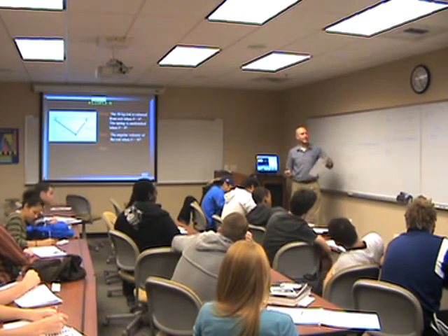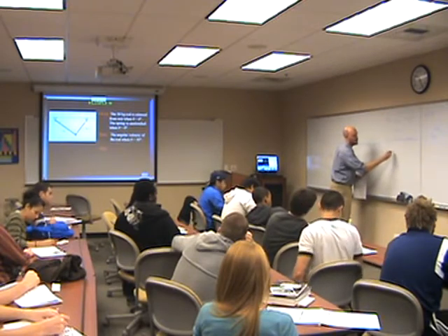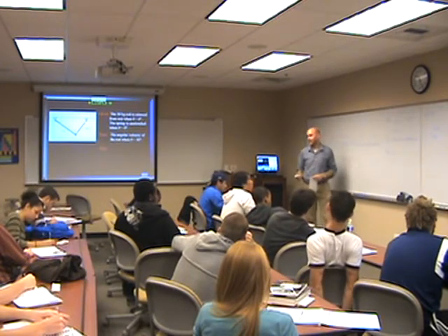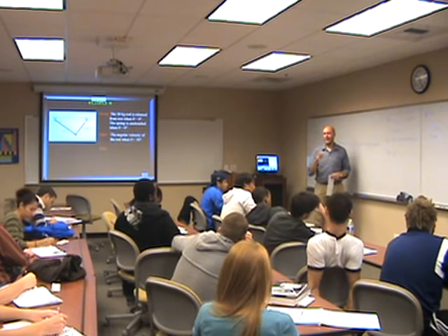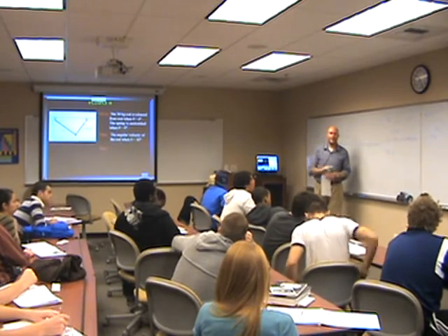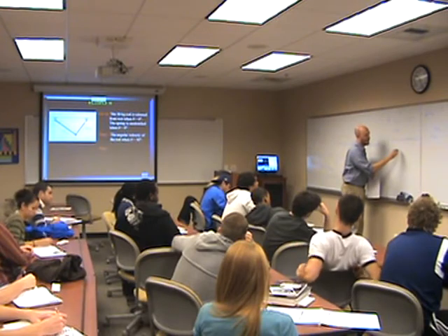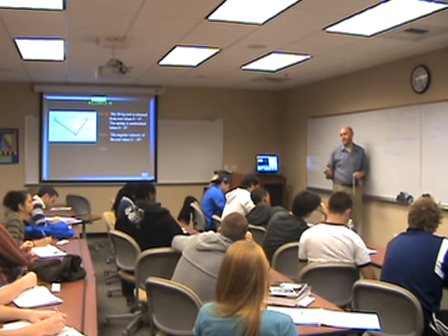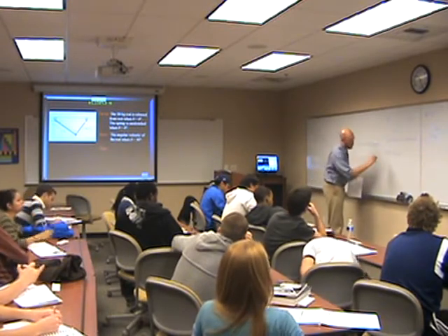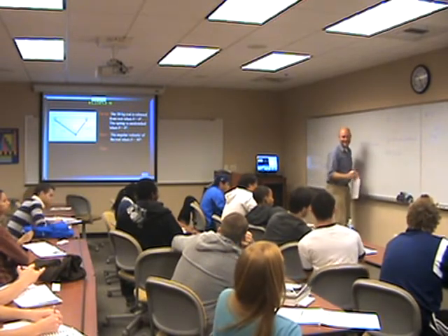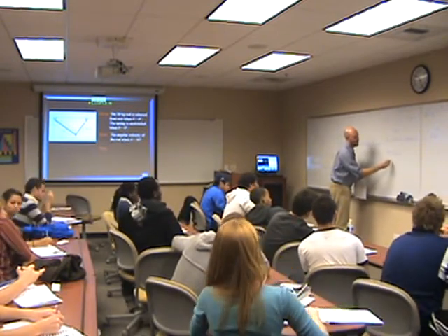It's equal to what? Well, initially it's 0 because we're at rest. So our final kinetic energy is 1/2 times what? Mass... well, I_G. It's 1/2 I_G, or we are rotating now about a fixed point, so we can just use 1/2 I_O times omega squared. What is I_O? It's 1/3 m L squared.